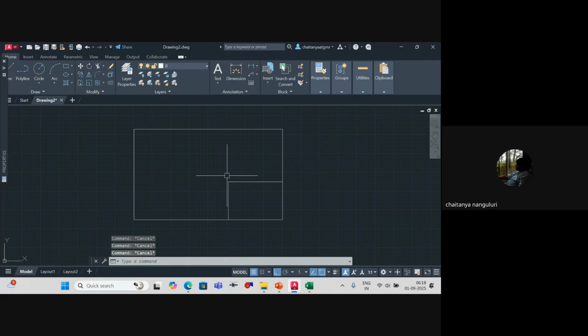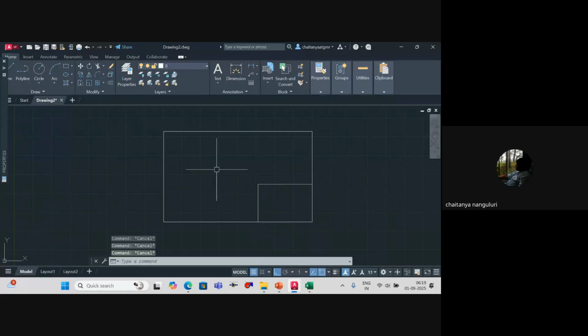Okay, I've got one more room at this particular location where I have to throw air into this space. Now, let's say I have two units in this. Let's say this room is a critical room where I have to do air conditioning 24 by 7. So when I have 24 by 7, don't you think I should have two equipment so that if one fails, at least the other one will come as a backup?